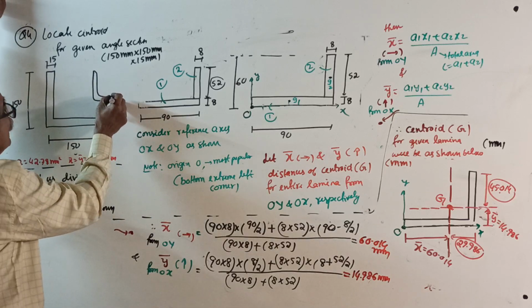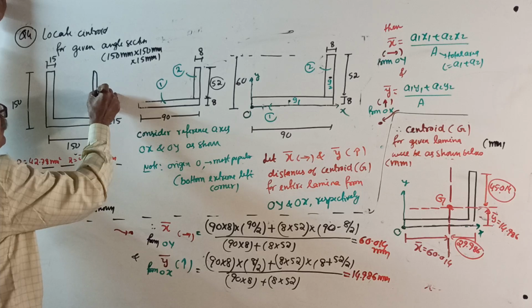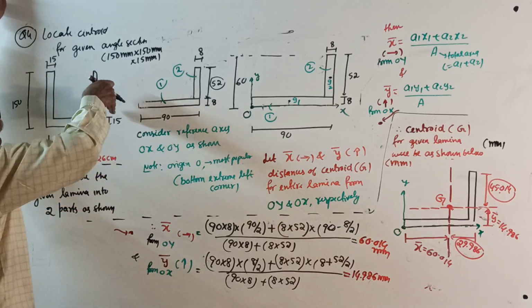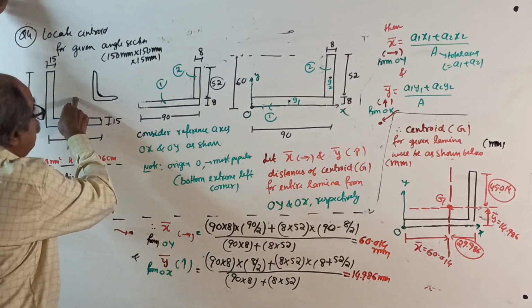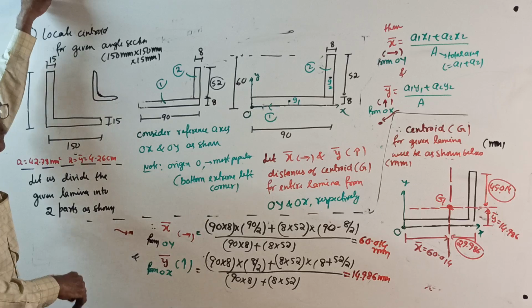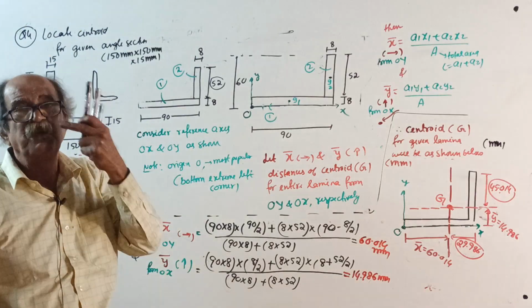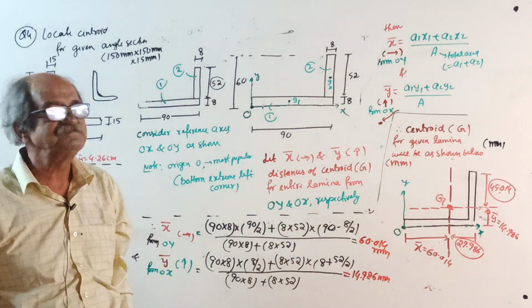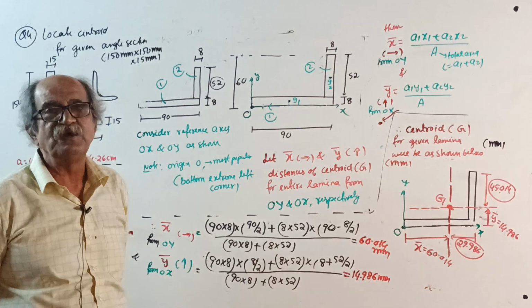They considered the curvature, and here at the root, some radius is there. It is not straight. So if you do by our engineering mechanics, exact same value will not come. And moment of inertia is 896.8 centimeter power 4. I know that answer, 896.8, because I used it more than 1,100 times.